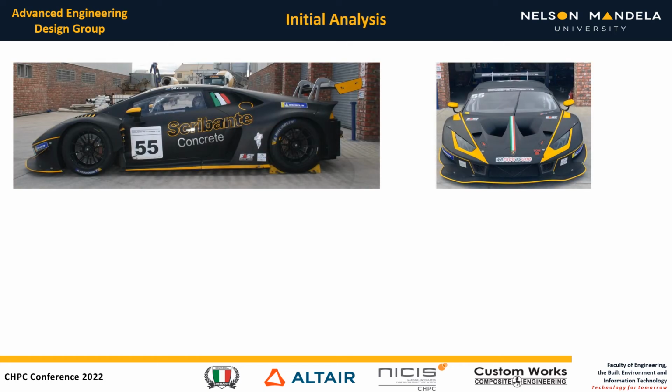Based on our initial CFD, as well as driver feedback, we identified areas of improvement. The drivers told us that they were experiencing understeer, which means that there is more grip, aka downforce, at the back of the vehicle compared to the front, which creates a clockwise rotation around the center of pressure. So naturally we focused on the front end, specifically the dive planes, as that was an easy place to start.